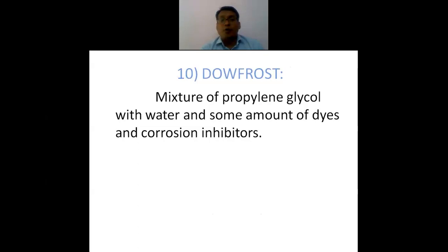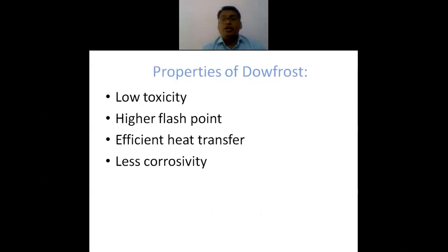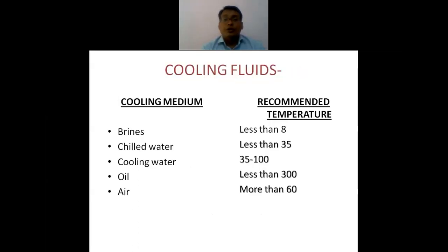Then Dowfrost. This is also a mixture of propylene glycol with water and some amount of dyes and corrosion inhibitors. So Dowtherm, Dowfrost, Therminol are the commonly used thermic fluids.